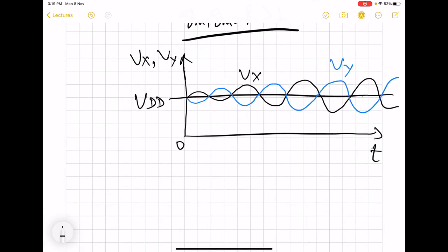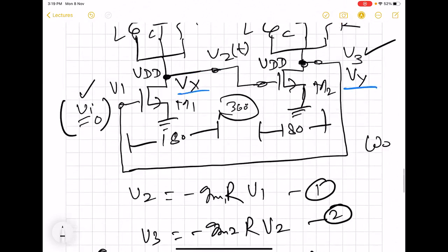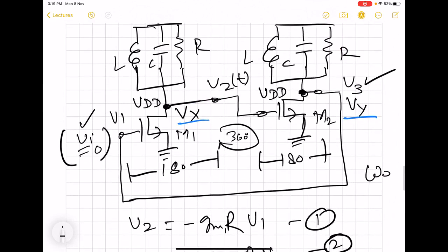So this is how the signal will grow. We will get a fixed value output after a certain duration. So the output will settle. We find that this circuit can act as an oscillator if we satisfy those criteria, especially the magnitude criteria. The phase will automatically get satisfied.